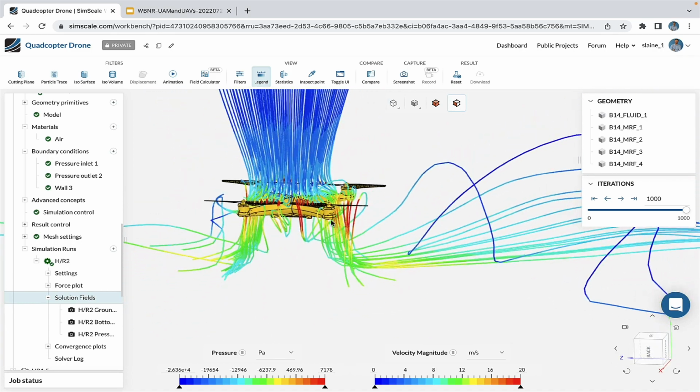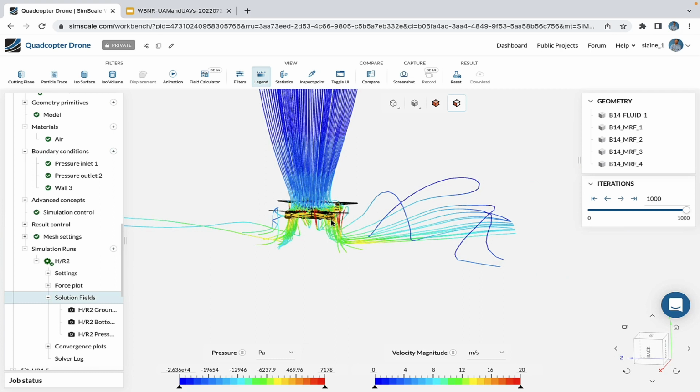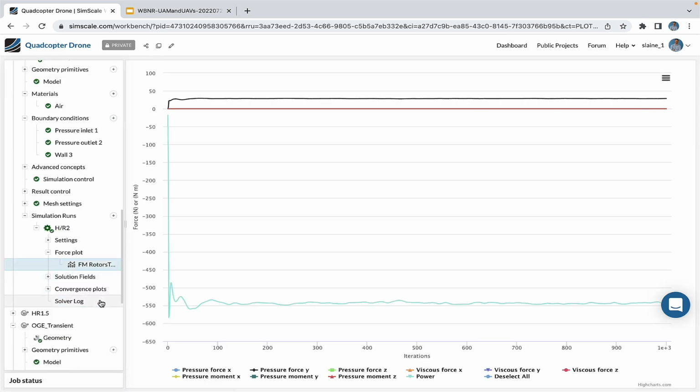The other important thing to consider is the actual power requirements. So CFD can help us understand how changes in the configuration of the drone itself can impact the thrust generated or the drag experienced by the vehicle, as well as its handling qualities. So you might want to investigate what happens if we have something like a 6-rotor aircraft or a 4-rotor aircraft.